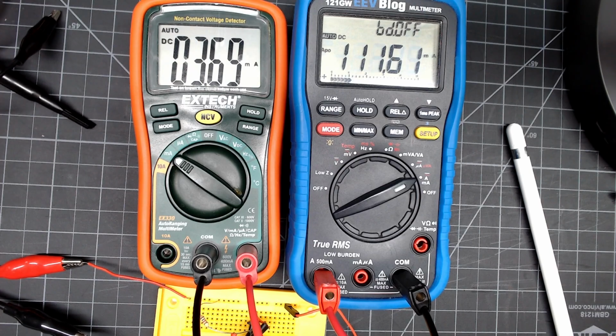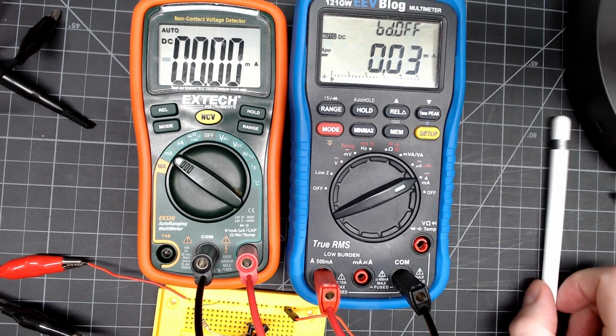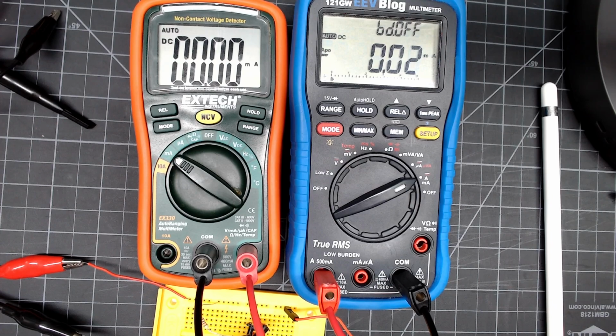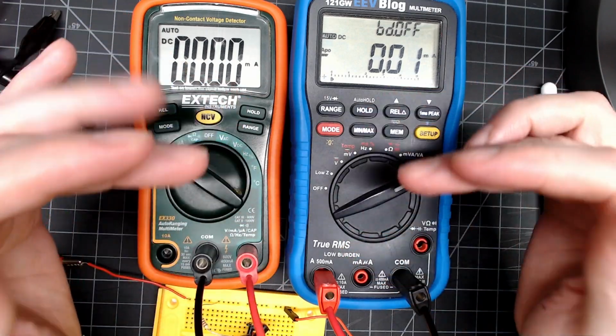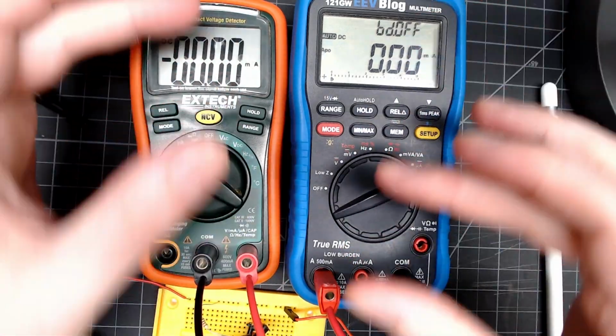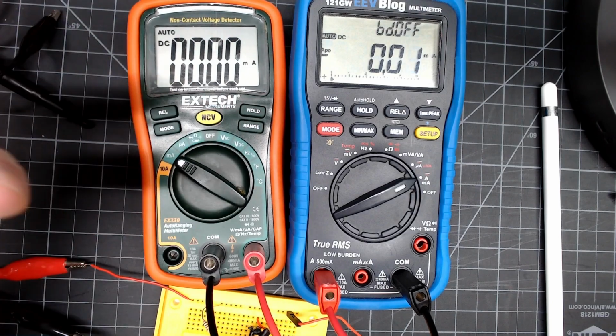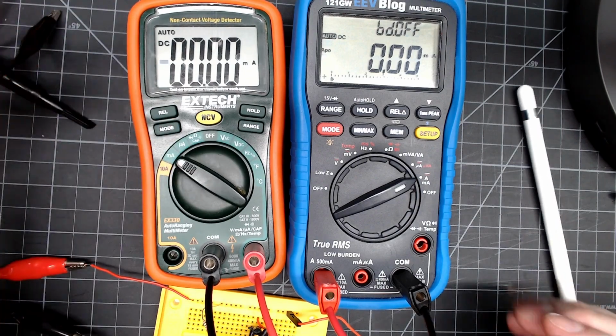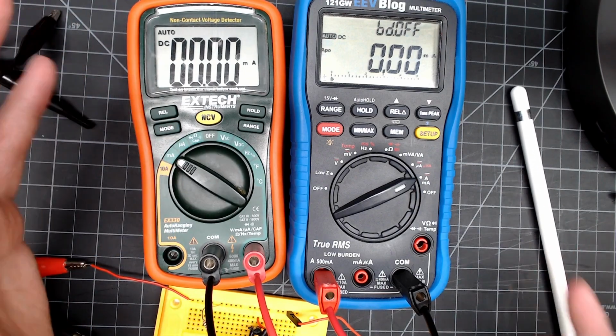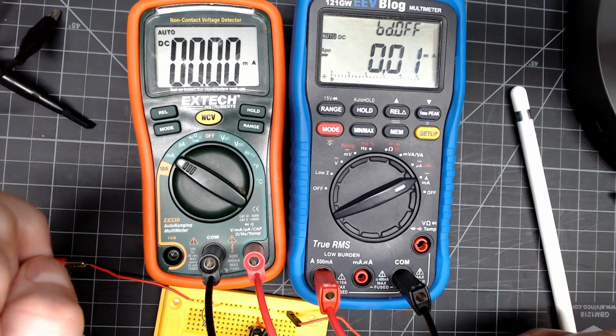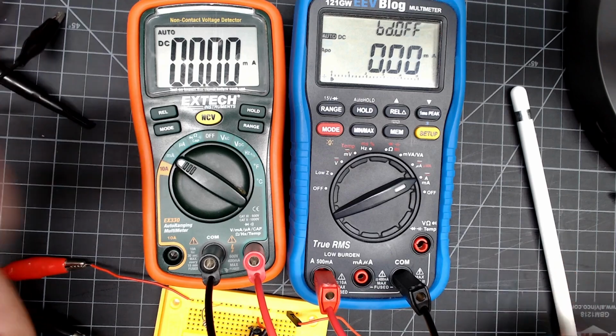So there we go. That seems quite simple, but it's the basic idea behind a transistor, how it works, and what we're going to use it for, which I'm sure is going to be building an H-bridge. We'll probably build 2 of them. I think there's going to be 4 transistors, and they'll work in concert to build this H-bridge. Basically, we have the same type of circuit forward and backwards. And that allows the microcontroller that I expect we'll eventually get to handle the 110 to 120, probably more when it's under load, probably closer to 150-ish milliamps that the motors are going to need without burning out the microprocessor.